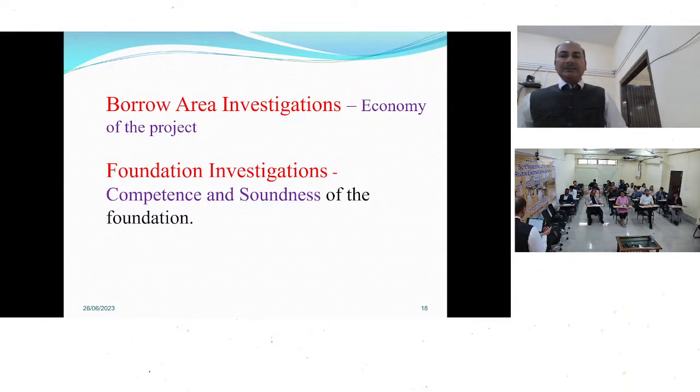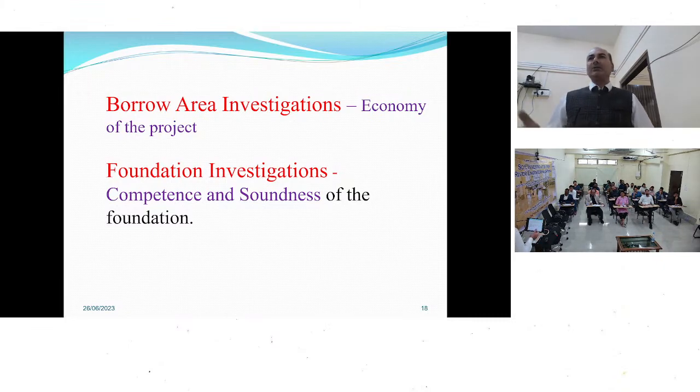The economy of any project depends upon the location of the borrow area. Suppose your borrow area is quite far from your site, then the lead will be quite high, and it will increase the cost of construction of the dam.